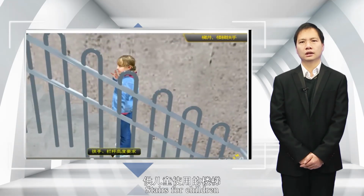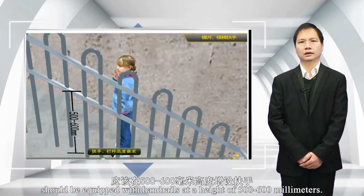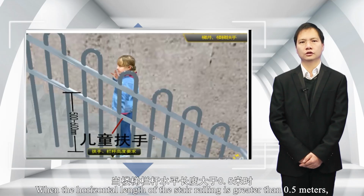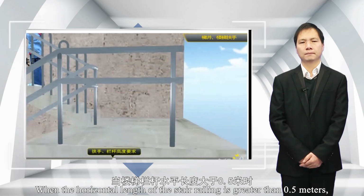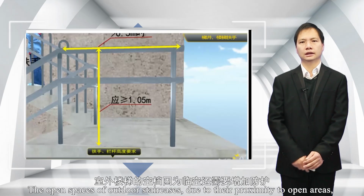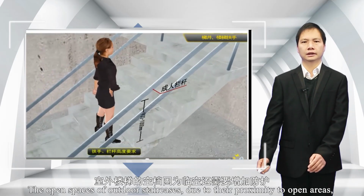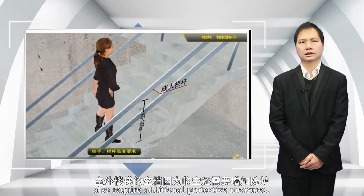Stairs for children should be equipped with handrails at a height of 500 to 600 millimeters. When the horizontal length of the stair railing is greater than 0.5 meters, the handrail height should be greater than 1.05 meters. The open spaces of outdoor staircases, due to their proximity to open areas, also require additional protective measures.